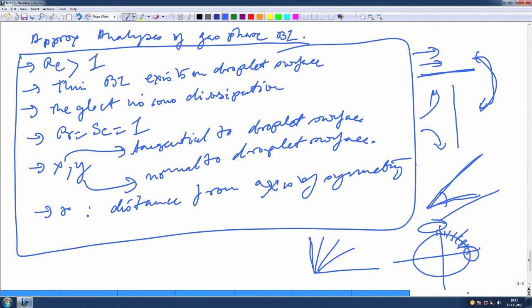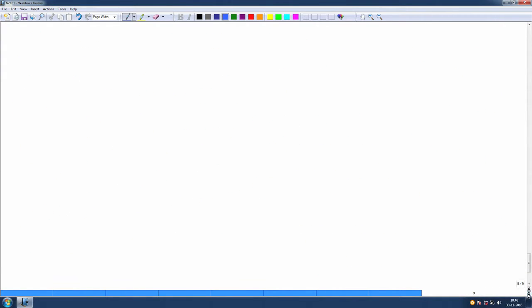If you take this section out, you will find that it is like a wedge of a certain angle, got it. So, we can use the Falkner-Skan class of solutions locally to solve the boundary layer, because the droplet in pieces, locally, behaves like a Falkner-Skan class of solution. Okay. And there are extremes like this and this, where it behaves like a normal flat plate boundary layer or like a stagnation flow solution. Okay. So, let us write the equations which will be useful.